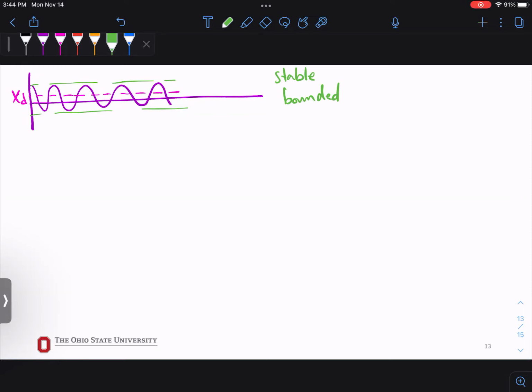This time, to achieve stability, we want to look at the velocity, because to stop at x desired, what does it mean? It means that the velocity of the system has to be 0 at that point, right? So if you think about some x dot, which is the velocity, we need to introduce a force that will be equal and opposite in direction, applied to the system at that x desired position, so the system will stop.